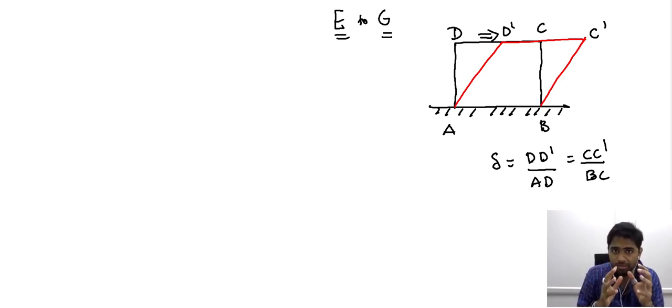Because we need to relate Young's modulus to shear modulus, we have started with the shear deformation, but since we need to include the Young's modulus, which is exclusively associated with tensile or compressive loading, we need to identify a distortion in this sample that is similar to that of the tensile and compressive distortion.